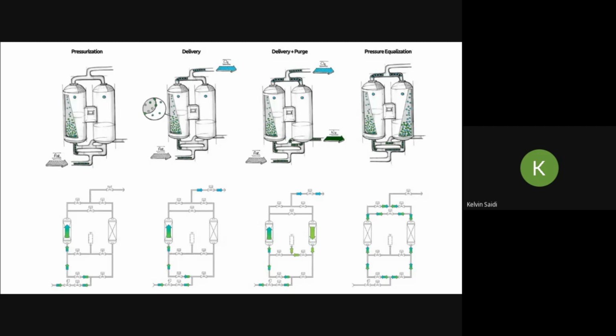After the depressurization process, the sieve bed is at low pressure, and while most of the nitrogen gets back into the air during this cycle, there is some residual nitrogen in the sieve bed that needs to be forced out. The process of forcing out this residual nitrogen from the sieve bed is called purging, and this is our topic of interest. So purging happens for two purposes.